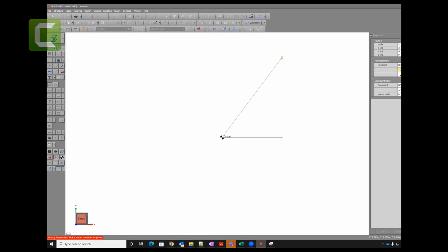So if I hold something very tight, the point, I'm talking about point again. The student asked me a question. You remember that we need to have this point. I'm talking about that point being fixed in all directions. There is a pin here that fixes all the displacements. You can see the first 3 displacements are fixed. There is a rotation fixed about the x-axis, but the rotation about y and rotation about z is allowed.